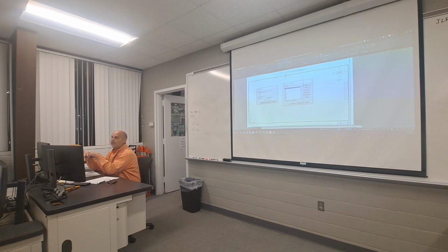We would go through and do that, and then we would save it, maybe 1/4 inch equals a foot. We would put that scale factor in there, that magic number. And then we would open that one up and we would do new. When we picked new, we just made sure that one was lit up. All we had to do was go change that scale factor, that magic number. And boom, there was our new. But we had to make a scale for each one, for each scale we used.